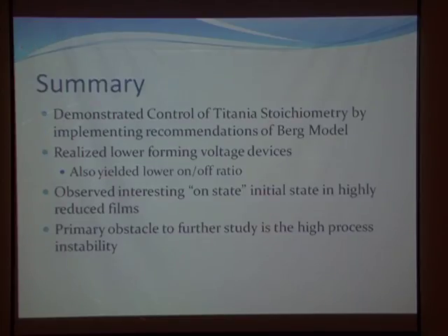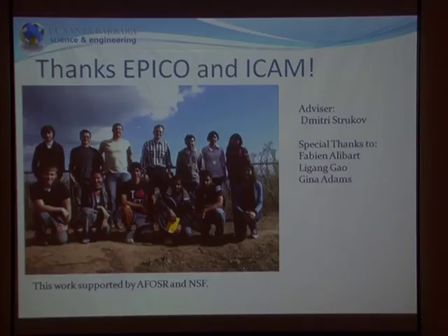And so in summary, I demonstrated control of titania stoichiometry in films by implementing recommendations of the Berg model. I realized lower forming voltage devices, and I also yielded a lower on-off ratio in general. And I observed an interesting on-state initial state in certain highly reduced films. The primary obstacle to further study is the process instability associated with target lifetime and instabilities in the mass flow controller accuracy. So thanks a lot.